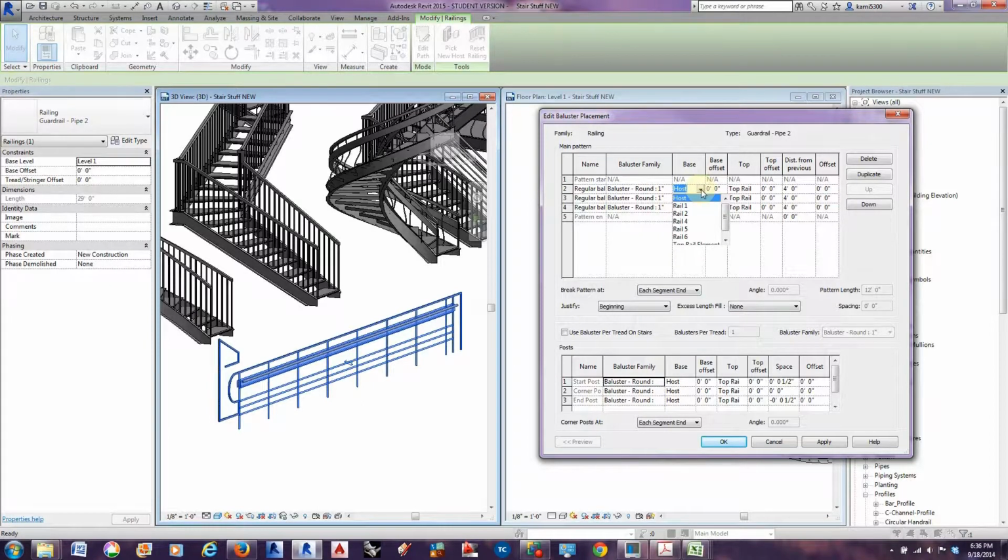And so you can change the heights, the bases of these based off of the horizontal rails that you placed. So you can have a real crazy pattern if you want. You can pretty much do anything. And then the top constraint would be the top rail, which is outside of this function, and that's this top rail here, which gets applied a little later on.